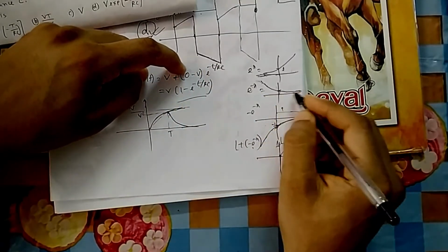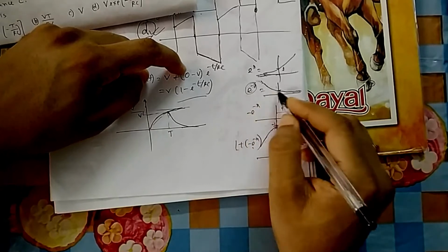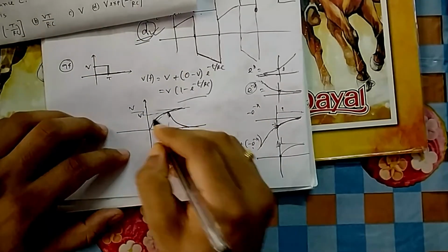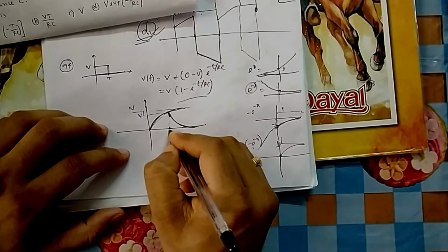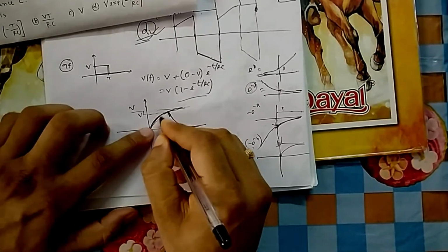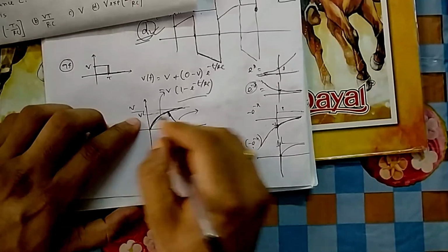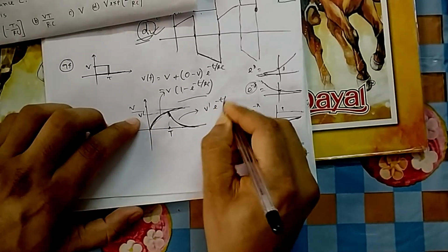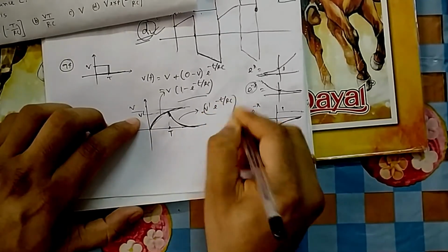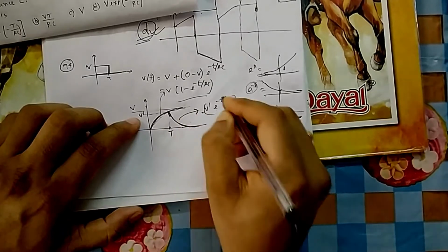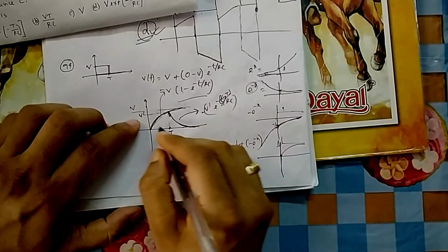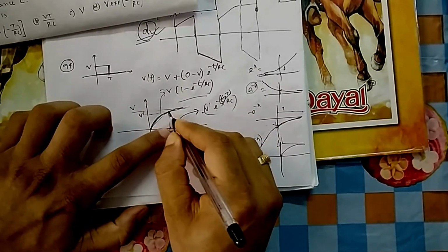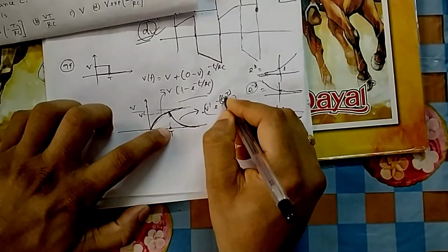So it will be this curve. V dash e to the power minus something. So it will follow this one. So this capacitor will charge up to this, and then it will decrease up to this. So what is the value? T. So here it will follow this curve, and here it will follow V dash e to the power minus t by RC. The expression is this one, sorry, not t, it is t minus T, because it starts from 0, and it is starting discharging from point T, so it is t minus T.